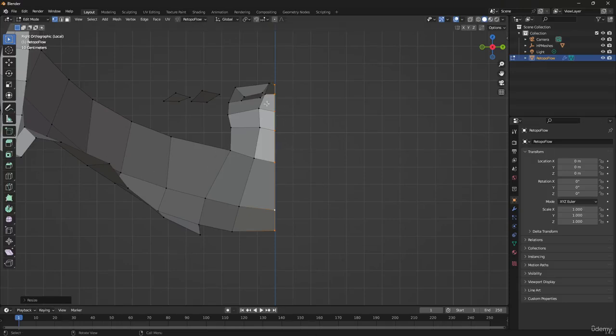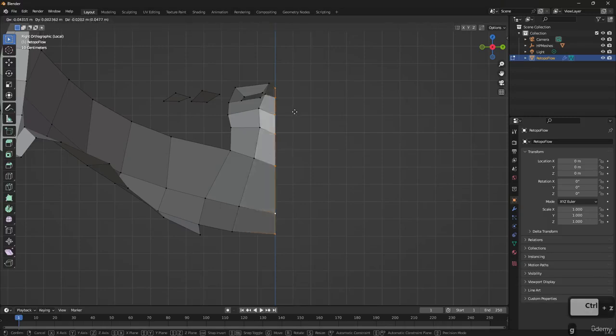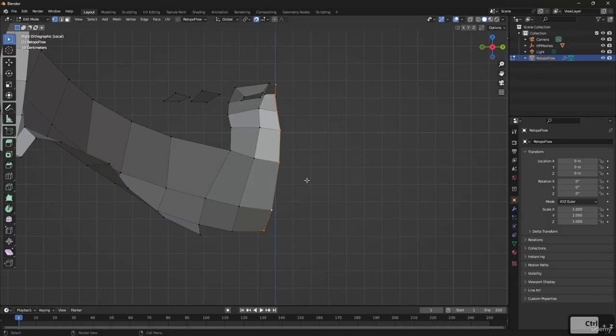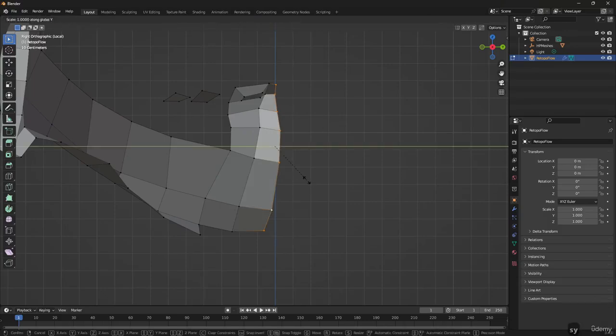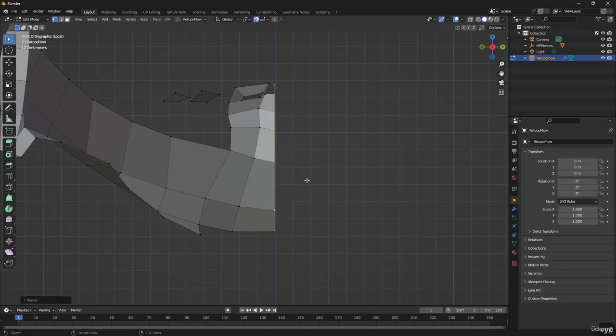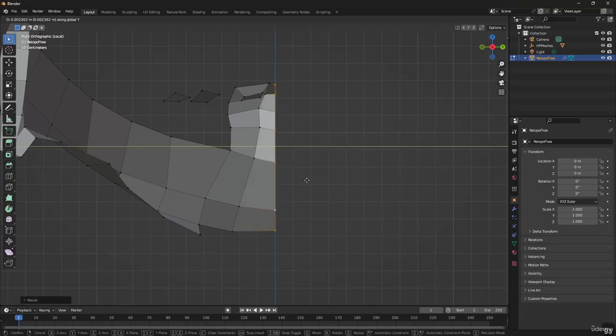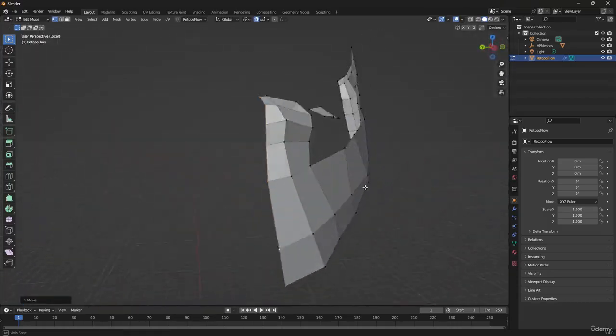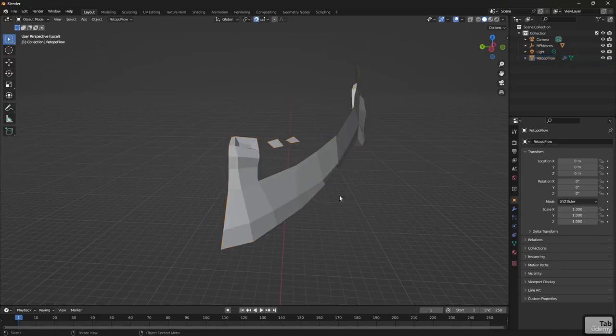y-axis. And then to make sure that they're on the center line, I'm going to turn on my little thing right here. I'm going to turn on absolute grid snap. I'm going to press a G and a Y. And that's going to make sure that they're exactly where they're supposed to be. So again, S, Y, 0, and then a G, Y. And we're just going to get them right there. So that should be the center line now.